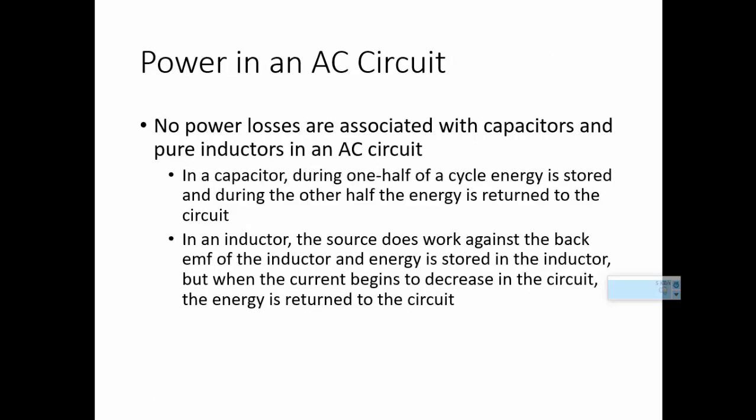Now, guys, we need to understand that no power losses are associated with capacitors and pure inductors in an AC circuit, because they have this charging and discharging mechanism. In a capacitor, during one half of a cycle, energy is stored, and during the other half the energy is returned back. In an inductor, the source works against the back EMF and the energy is stored in the inductor. But when the current begins to decrease in the AC circuit, the energy is returned to the circuit.